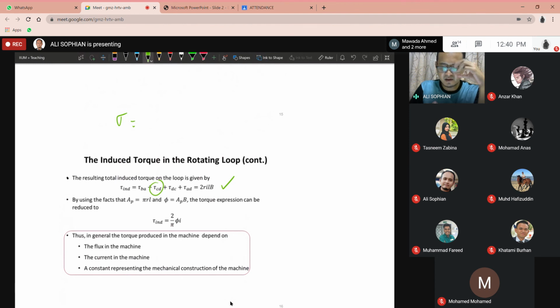something was not right here. You got AB, C, where's BC? This is BC. And then CD and DA. Okay, this is the wrong one. For the segments at the front and the back side of the rotor, the torque will be 0. So this will be 0, and these two will be 0. And these two have values, which is RILB. R, because we multiply ILB by R to make it into torque. Torque is again R times F, basically, if they are perpendicular.